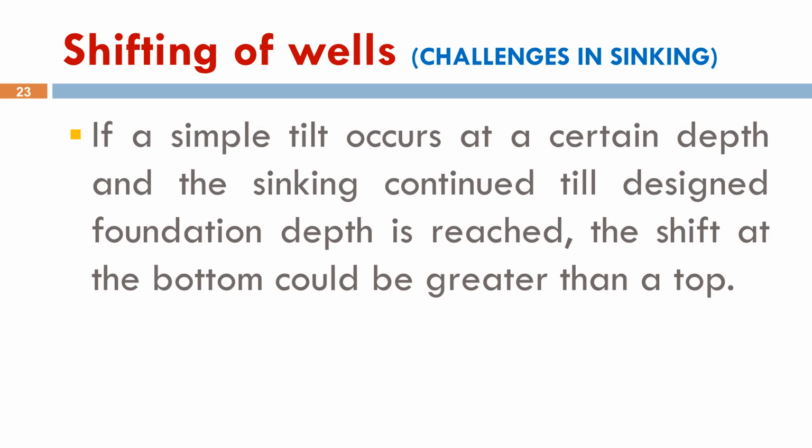To prevent this, engineers continuously monitor the well's verticality and position throughout the sinking process. If any deviation is detected, corrective measures are taken immediately, ensuring the caisson reaches its design location accurately and safely.